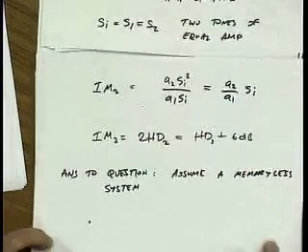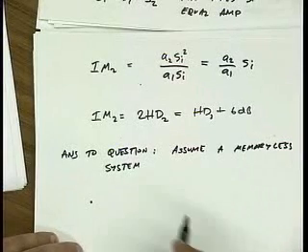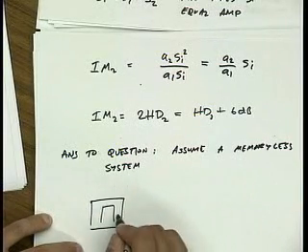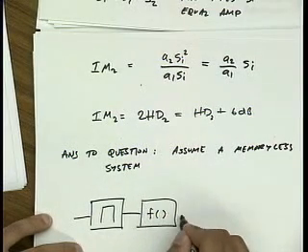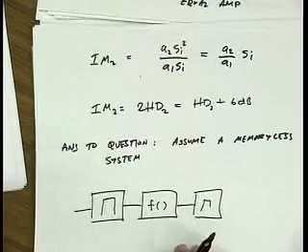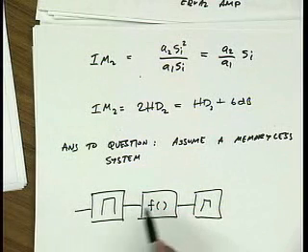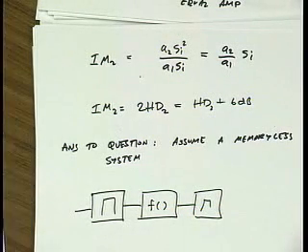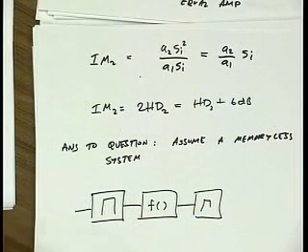It's flat. Now, you might say that's a really gross approximation, but what we're doing is we're separating our system into, let's say, filtering, and then nonlinearity, and then maybe filtering. So if we do have an LC tank at the input or at the output, we would actually apply it before and afterwards. Okay, that's a great observation. Anything else? Anyone else?